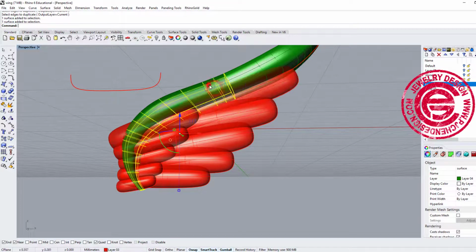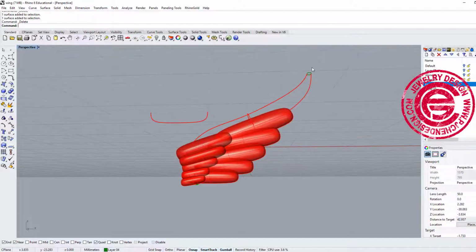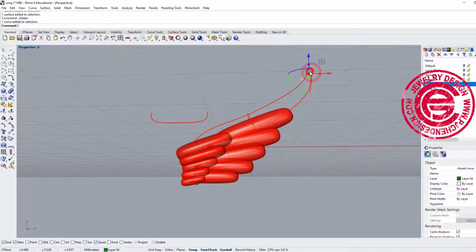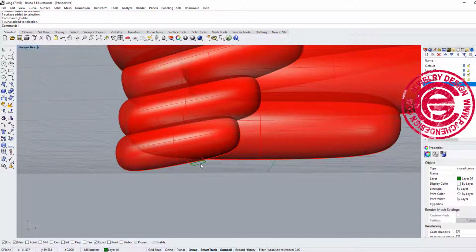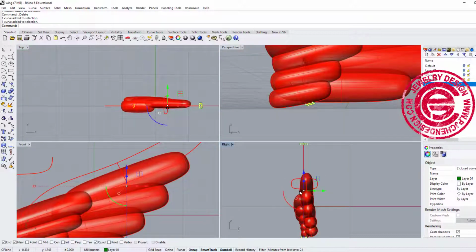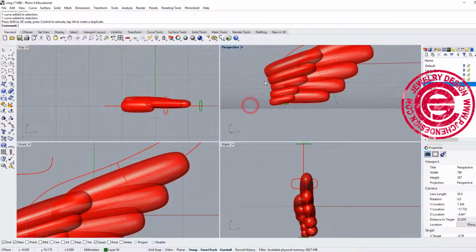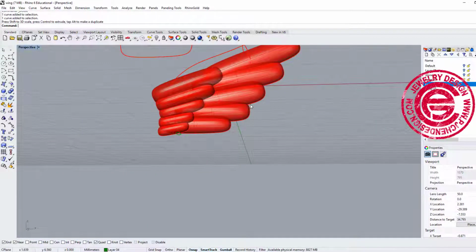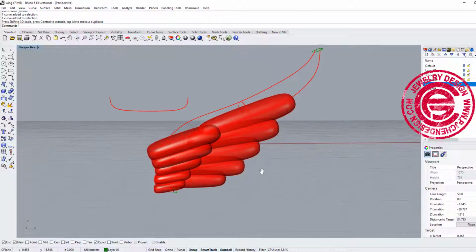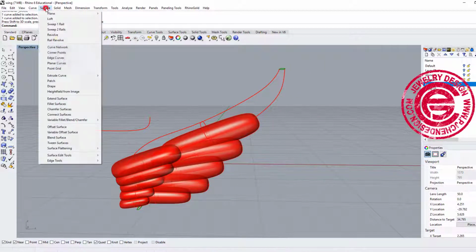We're gonna delete the surface we did and the surface over there, and we are going to use this new profile here and new profile over here, and let's make it a bit taller by stretching them 1D, so then I can have them taller. I always create a surface first and find a curve, delete the surface and use that curve. So let's try one more time.